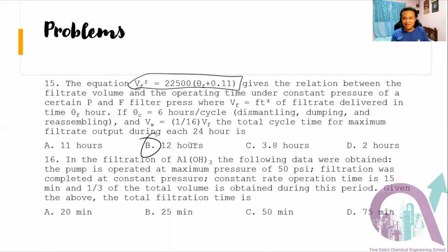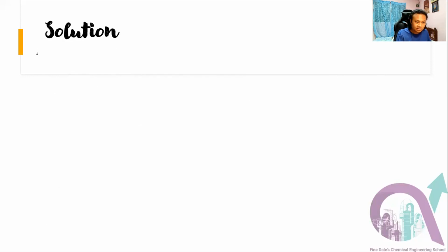So it requires the use of the root equation, but not really that intense in application of the root equation. So you have filtration of your aluminum hydroxide, and then you have your 50 psi pressure, and then the constant rate. So we are now dealing with CRF, CRF 15 minutes. And 1/3 of the total volume is obtained during this period. Given the above, the total filtration time is...